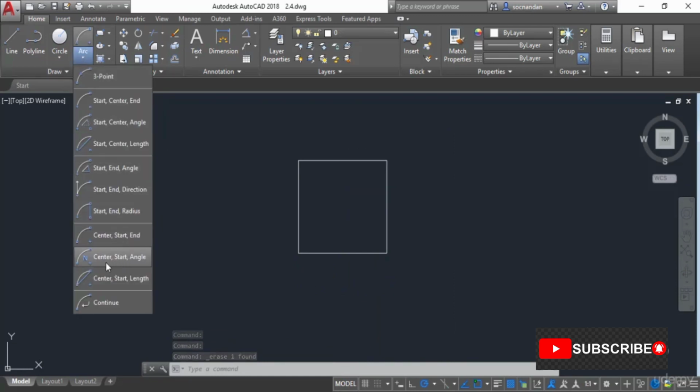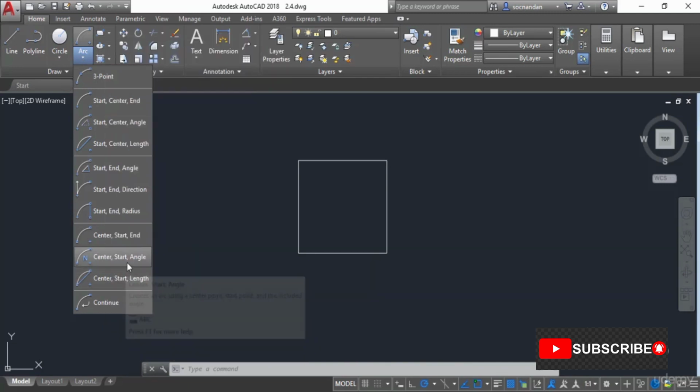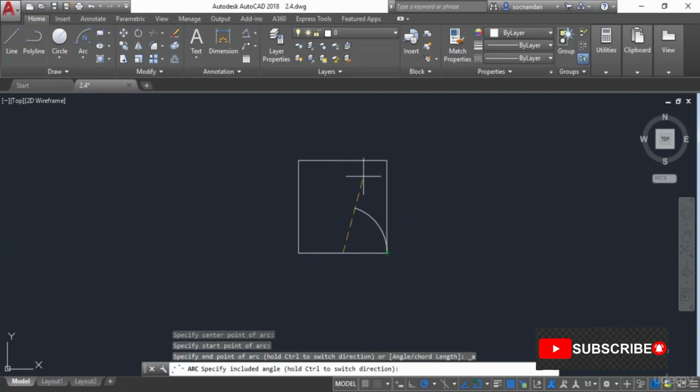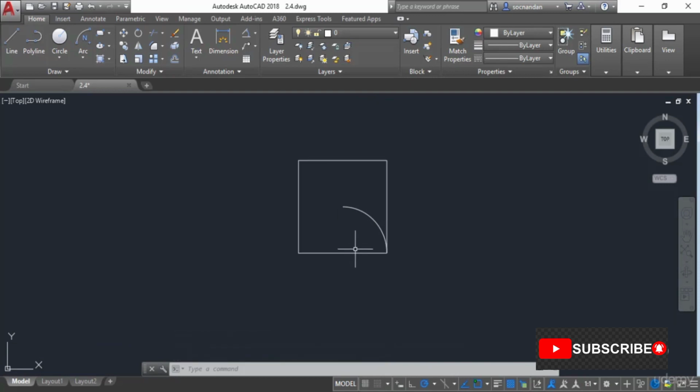So now the next option is center, start and angle. So here obviously we need to specify the center point and then the start point and the included angle. So here we have the center point, the starting point, and now we need to specify the included angle as we did in the previous case. But the only difference is that we are specifying the center point instead of the start and end points. So here also you can click anywhere to specify the angle, or you can simply enter the angle value just like this. So here I'm entering 90 and the arc is made with an included angle of 90 degrees. So if you make a straight line here, the included angle will be 90 degrees.